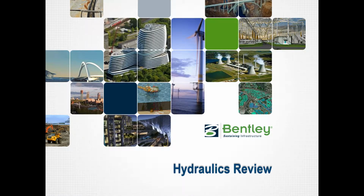All right, so the first step when you run any StormCAD model is that it calculates the hydrology, because our beginning point is we need to know the flows that are going to be coming into the system. And knowing those flows, we can then figure out, like Q equals VA, right? So we know the area, now we know the velocity, right? So we can figure out from the flows velocities, normal depths, friction losses, hydraulic grade lines, energy grade lines, etc. And how that's all happened, we're going to learn.